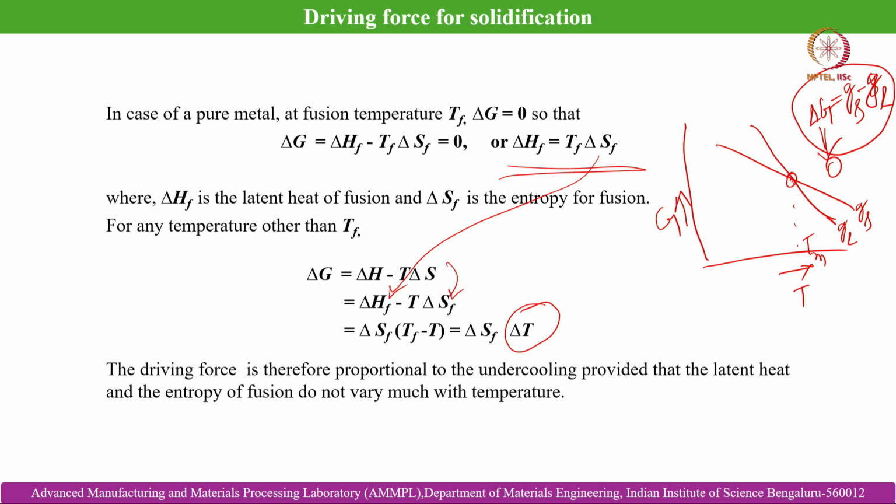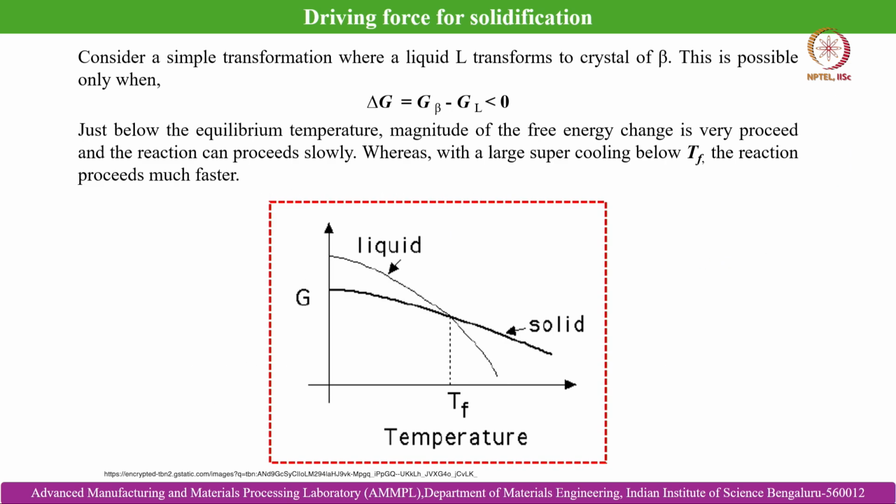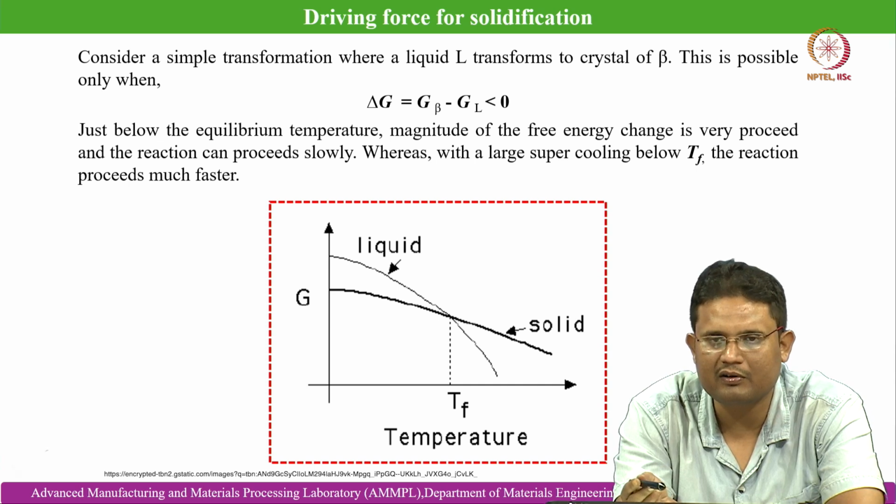So, the driving force is therefore proportional to the undercooling, provided that the latent heat and the entropy of fusion do not vary much with temperature. So, this is basically the driving force for solidification. Now we are trying to learn the fundamentals of the casting process that we have just discussed before in this class. Consider a simple transformation, as I have already shown you, where a liquid L transforms to crystals of beta.